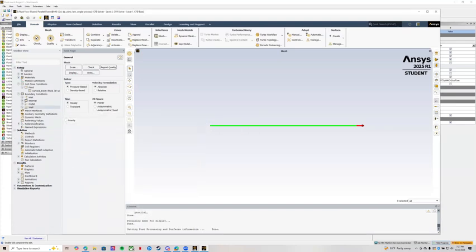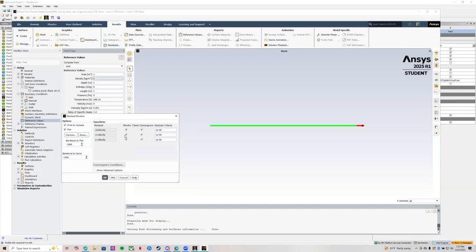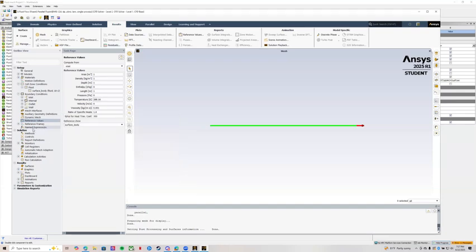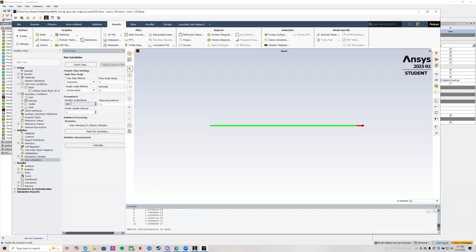Once that's done, all that's good. We go back to our reference values, double check that our inlet and surface body are all in the correct way and they have the right numbers, which we have everything. And then we're going to go to our results, double check our residuals are 1e-6. They're all good, so we can get out of there. We're going to go ahead and initialize this. Once that's done, we'll run our calculations with 200 iterations again. So it's done. We're going to go here, run calculations of 200 iterations, and let that load now.